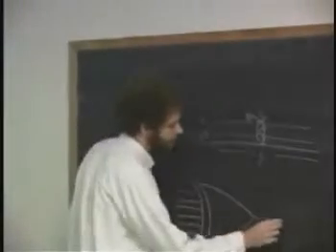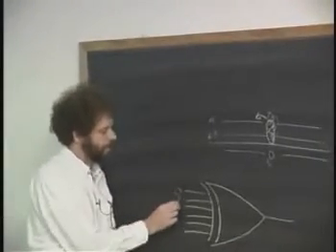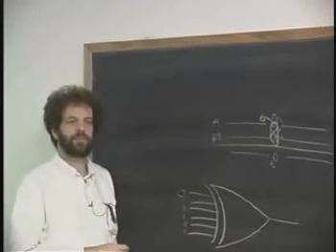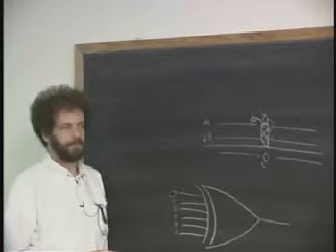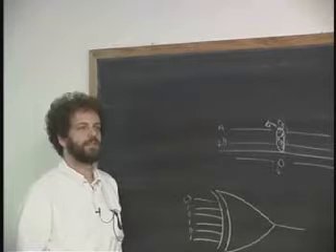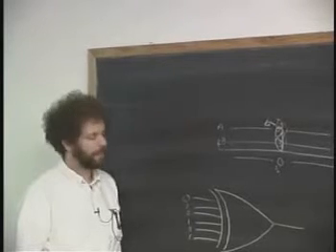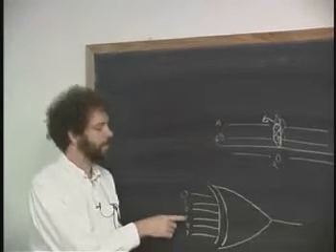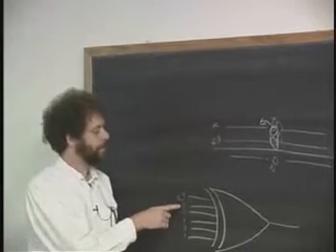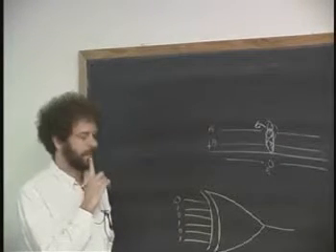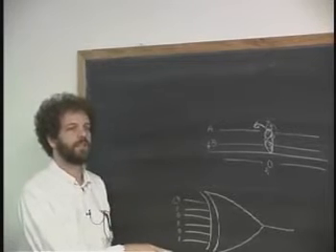If I have XOR of a whole bunch of bits, and here's an output, and let's say that I put in a bit string, 0, 1, 0, 1, 0, 1. What is the XOR of all those bits? Somebody said 0. Is it 0 or is it 1? What does XOR actually do? Gives you the odd or the even parity. That's absolutely right. It measures what's called the parity of the input here. It's counting how many ones there are, and it's seeing if the number of ones is odd or even. Now, is the number of ones here odd or even? Odd. So what is the XOR of all these things going to be?